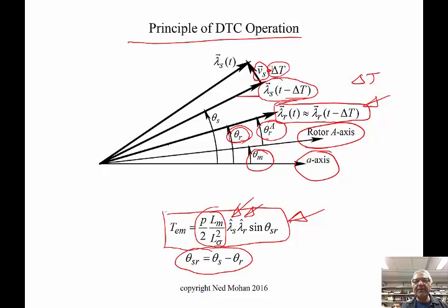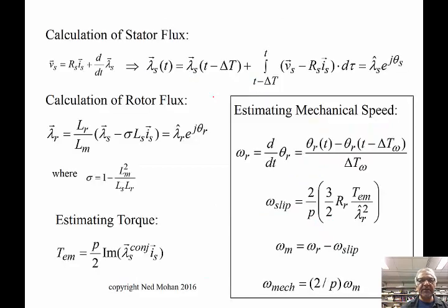For this particular time, we are applying it perpendicularly here, let's say, so it is going to change the position of the stator flux linkage space vector, but not the amplitude very much, because these two vectors, this one and this one, are perpendicular to each other as much as possible. Okay, so that's basically the idea of direct torque control in an induction machine.